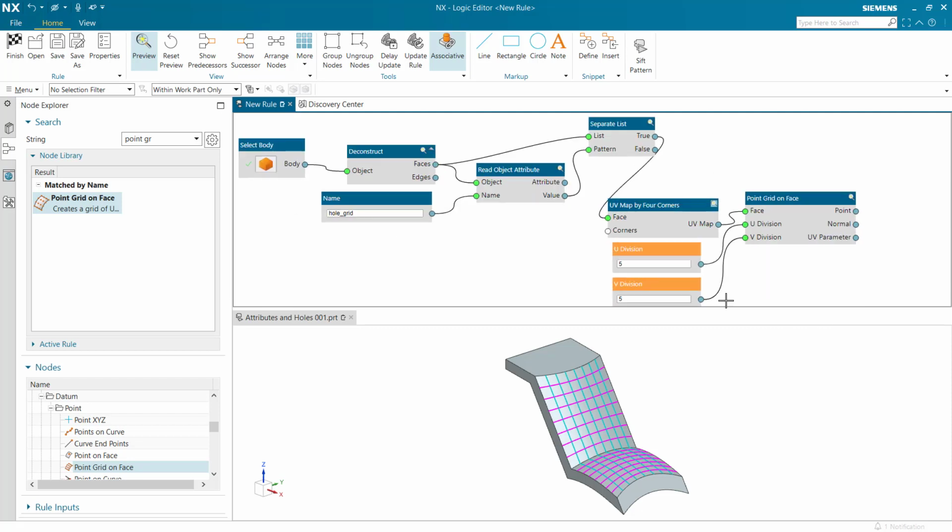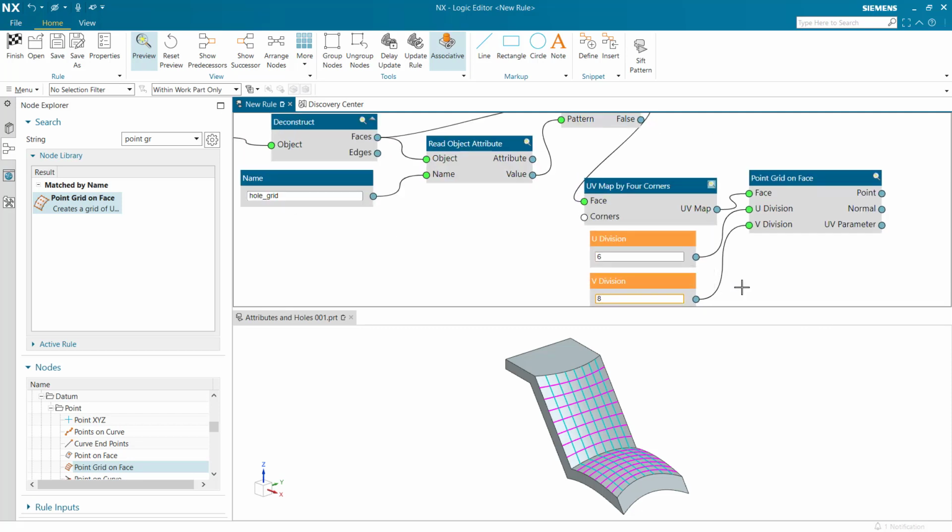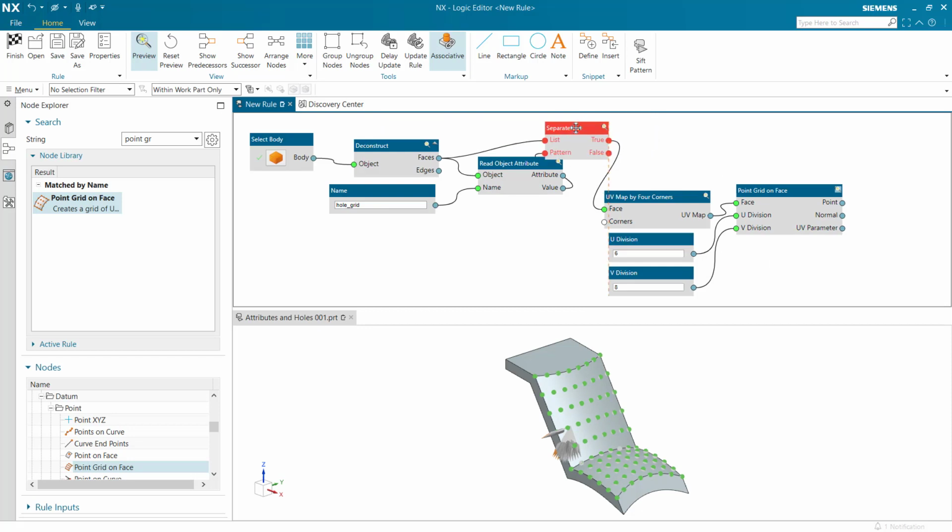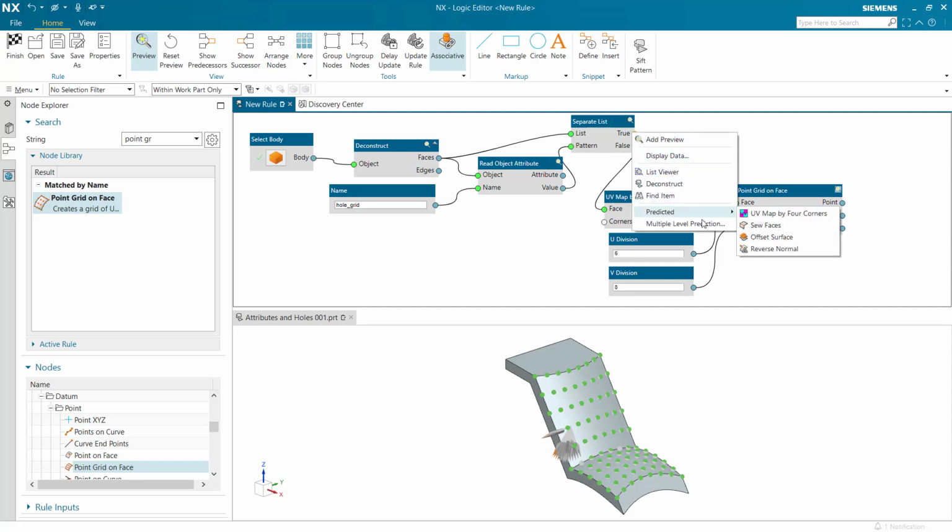On visual observation, we find that points are generated on each face with this grid density. But we want the combined shape to have that many holes, and not each individual face. We shall sew the faces to create a sheet on which this criteria shall be applied.